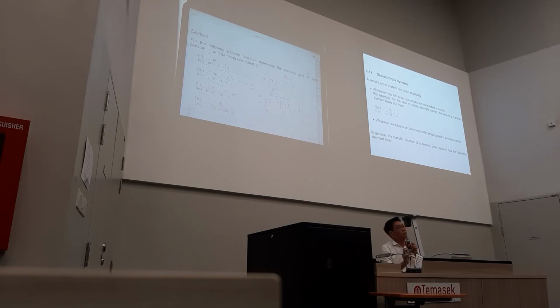I expand the bottom part: 0.25 multiplied by s becomes 0.25 s squared. 0.25 s plus 1 s is 1.25 s. The last one, 1 times 1 becomes plus 1. So I expand the bottom, and I have a new arrangement: 10 divided by 0.25 s squared plus 1.25 s plus 1.